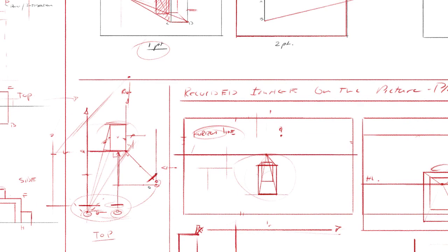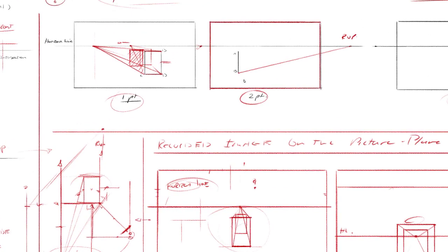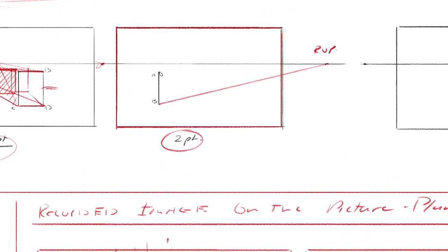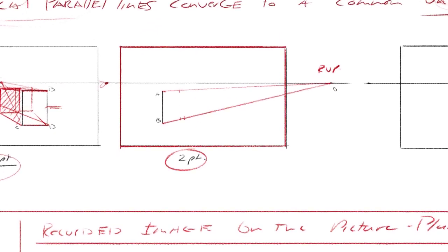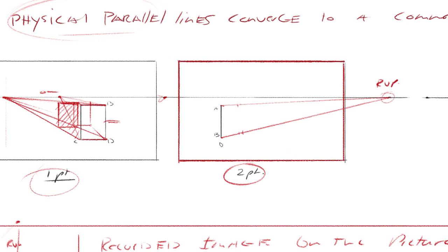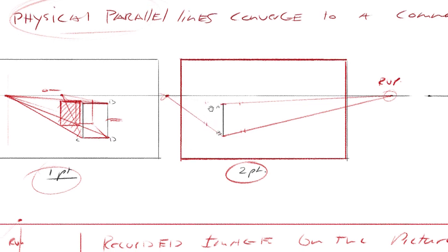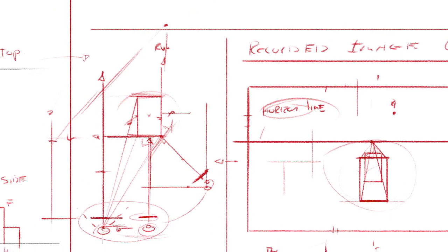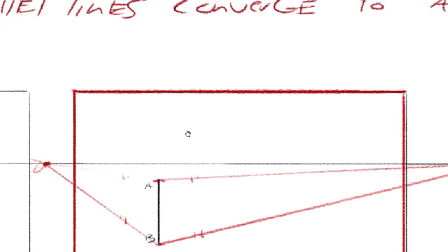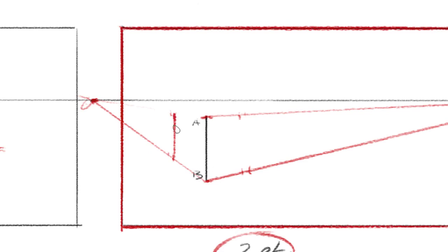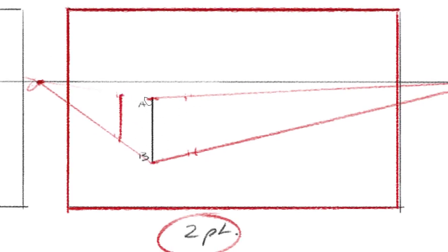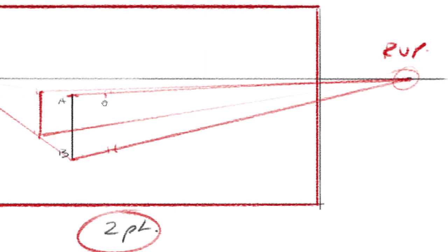So there's a vanishing point there, and it's a 2-point perspective, 2 vanishing points. And I'm going to connect the top as well. Okay, so now I have these sets of parallel lines, and they all go to the same vanishing point. So it's important to stay in control of your drawing. Okay, these points connect to that side. Now I've got these sets of parallel lines that go to the left vanishing point, and it's these ones that we are looking at. Okay, now I'm going to estimate my depth, connect the point there, and the same thing, connect to the right. The left is already connected.